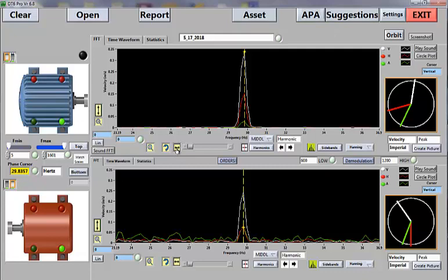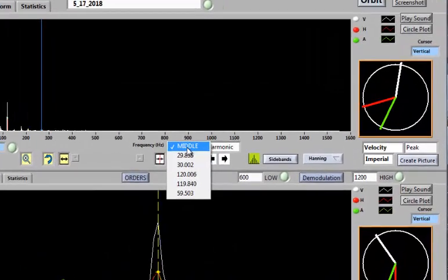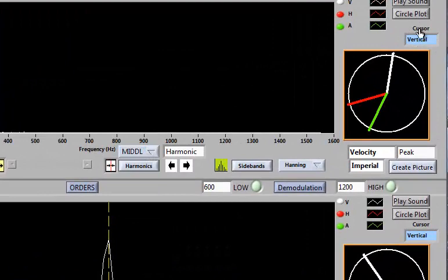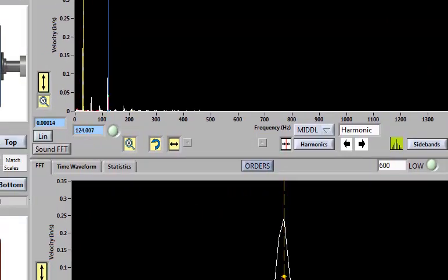If we zoom out with this auto scale button, we can see the waveform, and the first thing I would do is take this little blue cursor, which is responsible for all these little harmonic guys. So if I click this button, it'll show harmonics. So I'm going to take this blue guy and move it here, but sometimes on a tablet it's hard to move this, so we have this little thing here where you can click this, and for whatever cursor you have here, this basically decides which cursor the amplitude gets read. It's like the selected cursor, its channel.